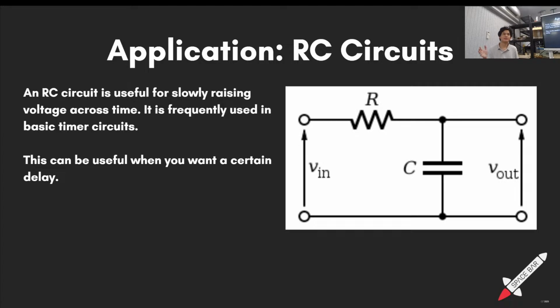By the way, the reason why the microcontroller might need this is because the microcontroller datasheet says so. There is no specific reason why this might be the case. Later I'll show you an example of when we actually use this on a microcontroller. But basically, RC circuit is for having something turn on after a delay. We charge the capacitor through the resistor, and that is what causes the delay.